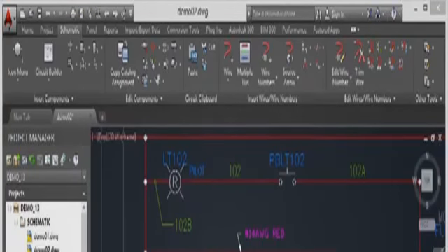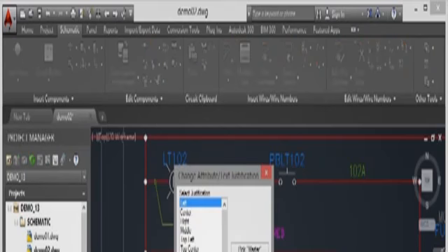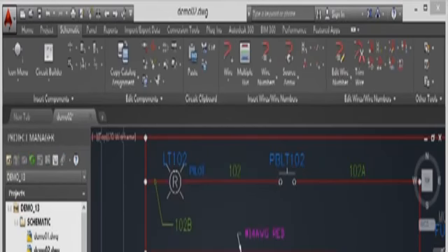Something that you can do, for example, with this power on down here, is I'm going to change both of those to a right justification and then move them. So I'm going to go up here again, change attribute justification, and I'm going to go right and OK it. Text attribute change to right, power, and then on. So they're both adjusted to the right. I then press enter to finish.